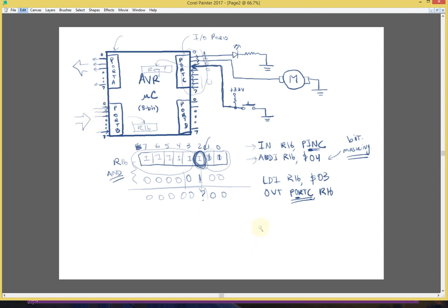All right, the thing about the in and the out instruction is that they write or read all 8 bits at once. Actually, we were just going to talk about writing. When we write, you use the out instruction, it writes all 8 bits at once. But if I'm going to mix some devices, where some of them are outputs and some of them are inputs, I don't want to have to create a bit mask. I just want to go directly to the bit at the pin level. I want to just turn that one bit on or off without doing anything fancy. How do I do that?